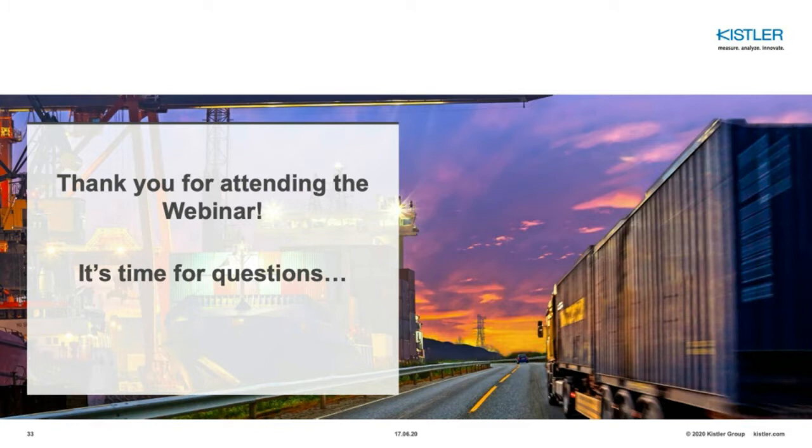It's really on the linear digital sensor, and there you get information like single or dual tire, the width of the tire, the lateral driving position, and whether the tire is flat or well inflated. All this information is gathered with this one linear digital sensor, and no additional sensors like piezo sensors at 45 degrees are needed. I think this is also something new, one of the innovations coming with this sensor, which needs to be well understood, and it's great that we can point it out again.